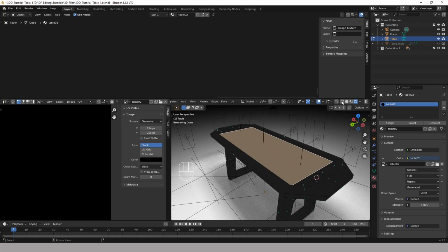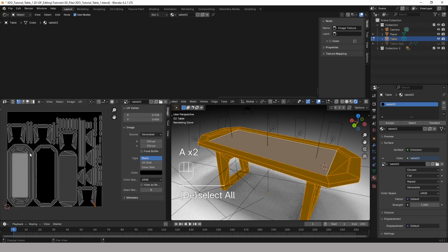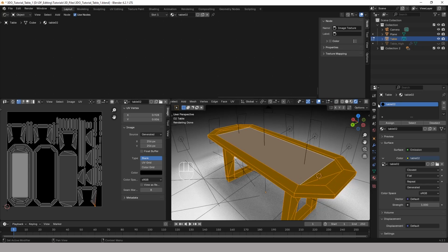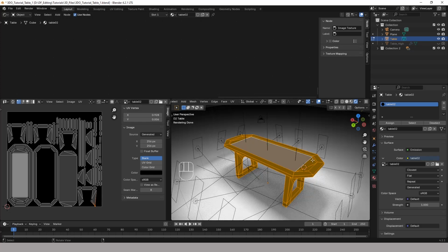But it's just something that you definitely need to keep in mind, because when it works great, you don't notice. When it breaks, you will notice immediately, regardless of what piece of software or operation you're trying to do. So we'll just make sure that one's turned off, that one's turned off. Select our whole mesh, and on the low res mesh, this is where we want to keep our one material named Table02, our one texture called Table02, because texture baking won't work unless there's an actual texture assigned to that object to bake to, which makes sense.